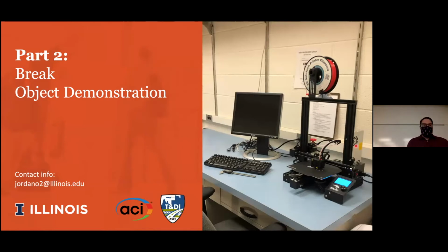So we asked in class how to select the infill percentage. We will cover that a little bit later in the step-by-step manual if you want. But it all depends on the time you have for printing and the kind of mechanical strength you need in your part. So I have a few examples here of different infills. I don't know if I can show them.